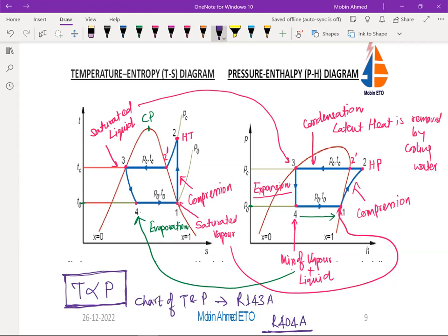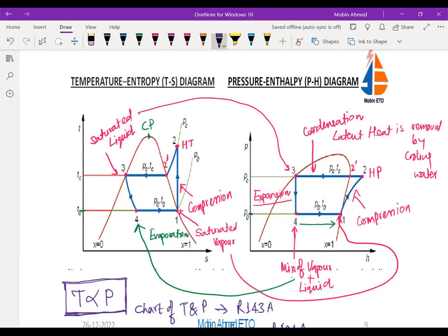So as per the different gases, they are going to have their own temperature and pressure charts of the refrigerant I'm talking about. So whatever pressure it is showing in the pressure gauge, you can calculate the temperature from that. Or if you know the temperature of the refrigerant, then you can calculate the pressure also, because both are directly proportional to each other.